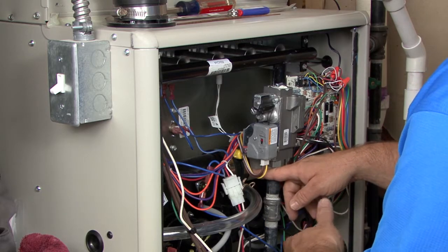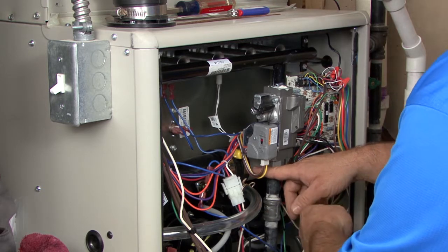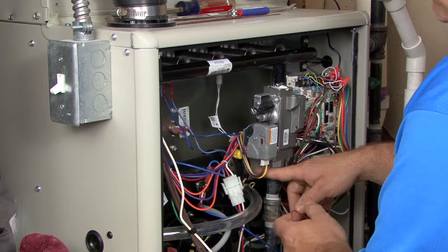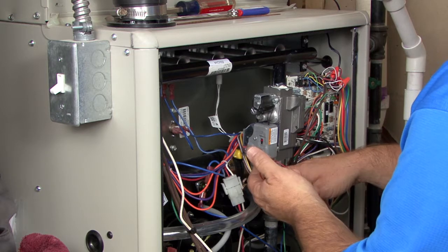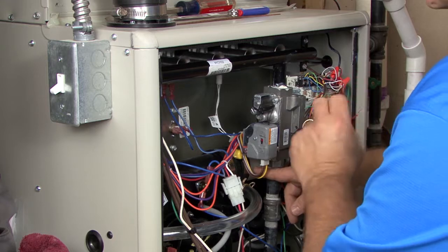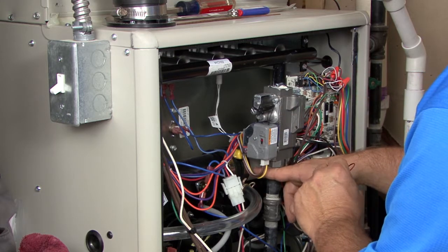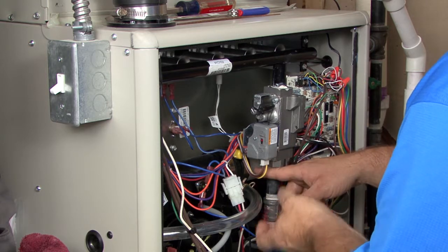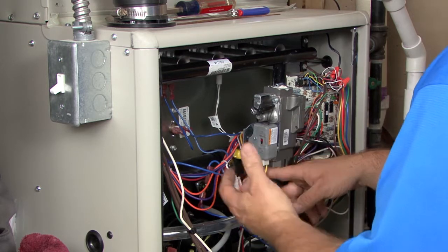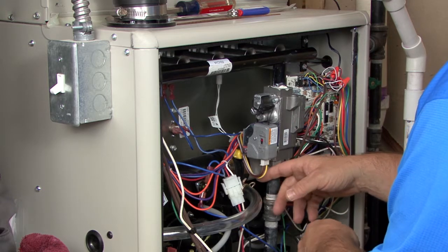And then the other thing I'm going to do, just so I don't have any air disturbance at all, I'm going to put a rag in that pipe just so that any air blowing down that flue pipe can't possibly get in that heat exchanger, because I don't want any airflow inside the cells of that heat exchanger. I just want static air in there. And with static air in there and blower air blowing around that heat exchanger, if I get smoke movement, then I know I got a breach.